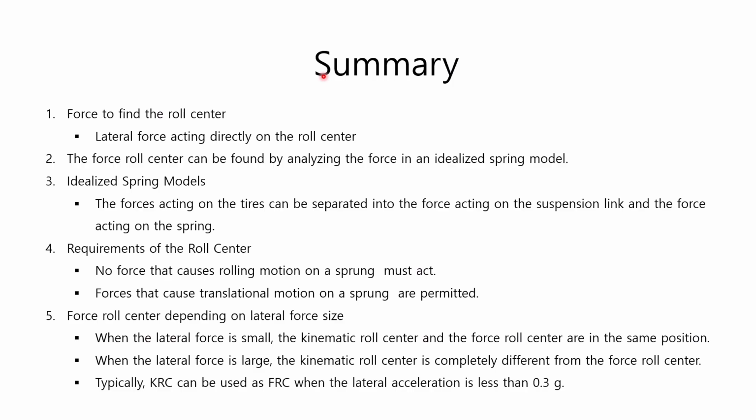Let's summarize the content of this video. The force needed to find the roll center is the lateral force acting directly on the roll center. The force roll center can be found by analyzing the force in an idealized spring model. Using the idealized spring model, the forces acting on the tire can be separated into the force acting on the suspension link and the force acting on the spring. The requirements for the roll center can be summarized as follows. No force that causes rolling motion on a sprung mass must act. Forces that cause translational motion on a sprung mass are permitted.